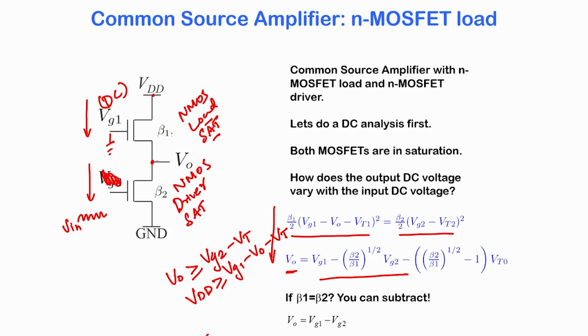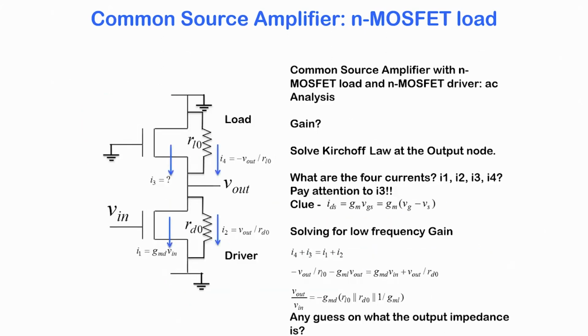So, let us take this case, and why have we chosen an NMOS device? The hope is that the NMOS device can be engineered through aspect ratio, through applying VG1 in a suitable manner, etc., to make sure that V out is always kept finite and the driver MOSFET is always kept in saturation, unlike the case of using a resistor. So, that is the hope, and we hope that this is going to give us large gain, because now we can use many more parameters to tune the resistance of the MOSFET, but let us see whether that works out.